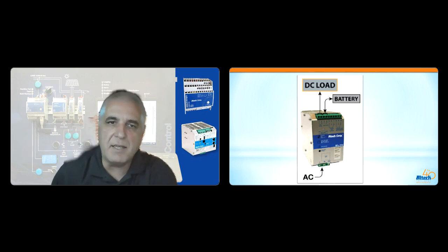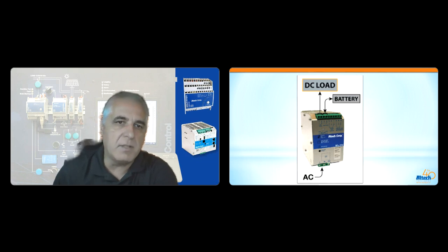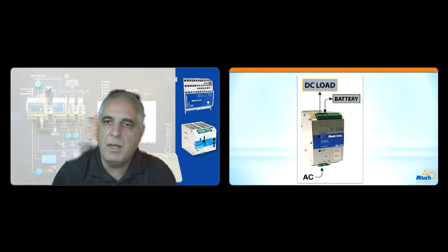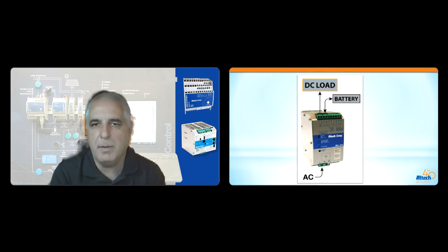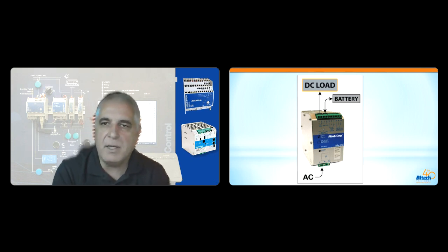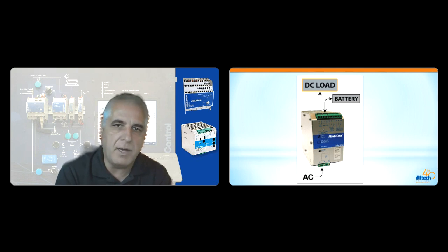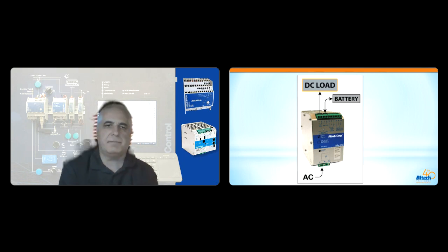The CBI series DC UPS products are an all-in-one device that includes a power supply, a battery charger, a battery management system, and a backup module, as well as integrated smart battery management firmware designed to optimize the available power by automatically allocating it to both the load, which is always the priority, and the battery. This automatic multi-stage operation optimizes and adapts to the battery status to provide a continuous power supply to the load and prevent the load output from being affected by battery conditions.